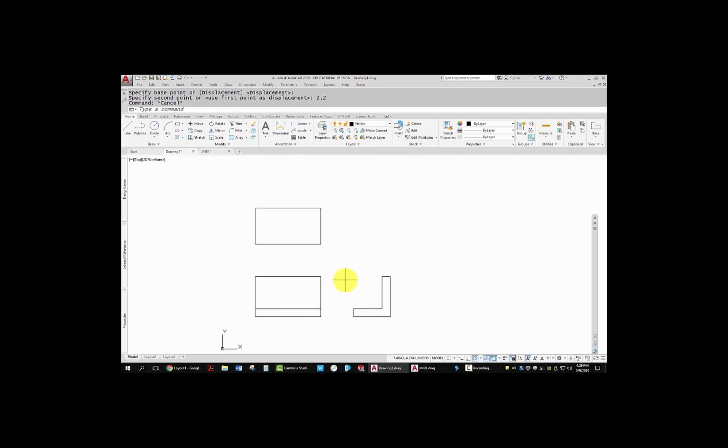Now I'm going to draw a miter line. The miter line is going to start at the intersection of this line and this line. I can do that one of two ways. I can highlight both of those corners and get two tracking points that I've acquired. Left click and start at their intersection, and then go up at 45 degrees.